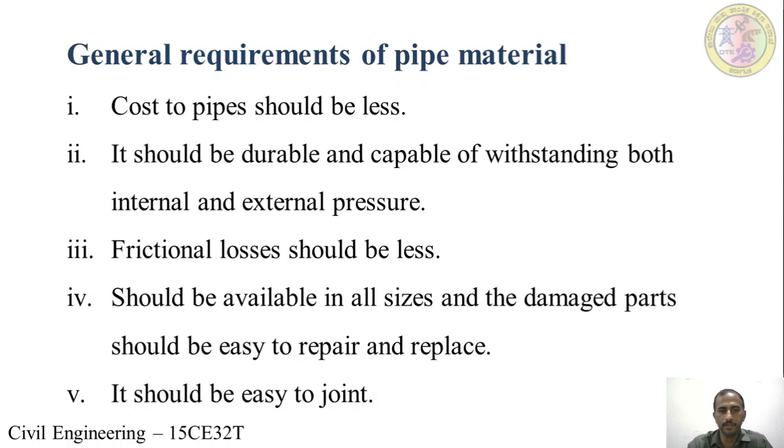Internal pressure is from the water flowing inside the pipe. It will cause the tensile force on the pipe material. Whereas the external pressure is caused by the backfilling material or the traffic over the pipeline.